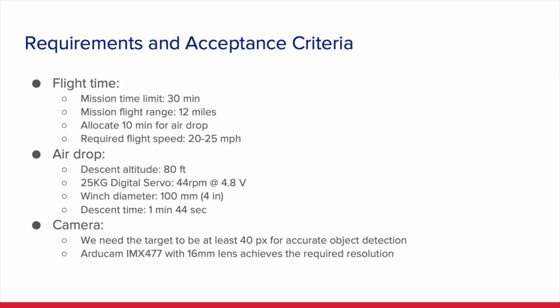For the camera, we need the target to be at least 40 pixels for accurate object detection, and we will be using an Arducam IMX477 with a 16mm lens to achieve the required resolution.